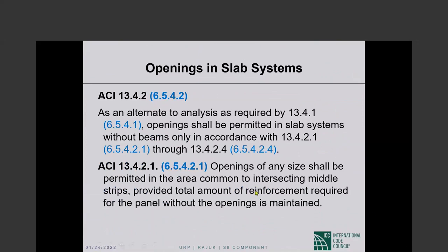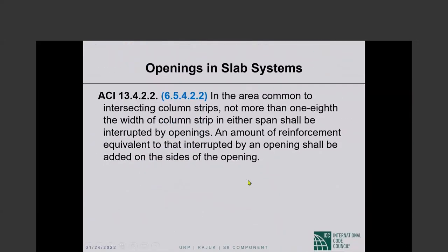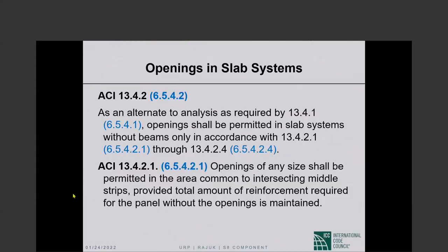Openings of any size shall be permitted in the area common to intersecting middle strips, provided total amount of reinforcement required for the panel without the openings is maintained. Yeah, whenever you put openings in, this is a recurring theme.